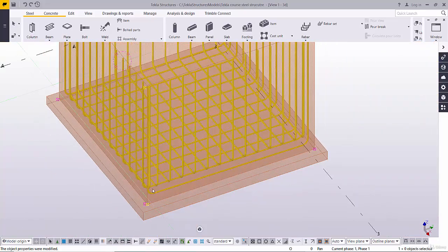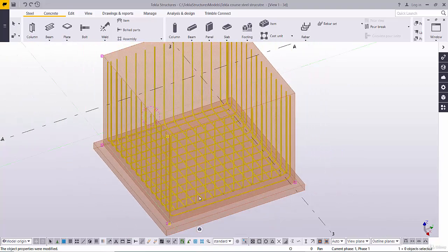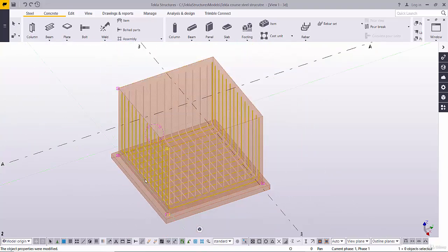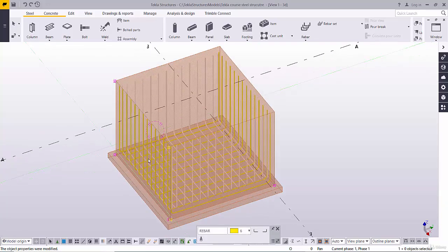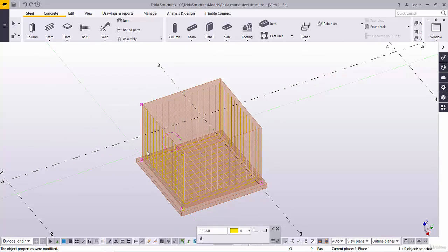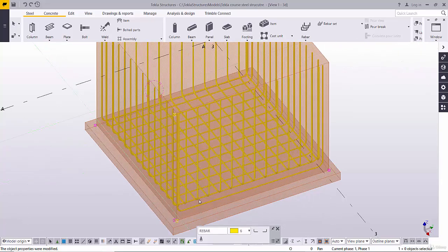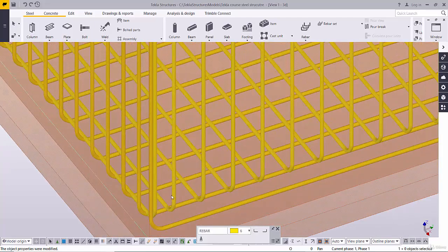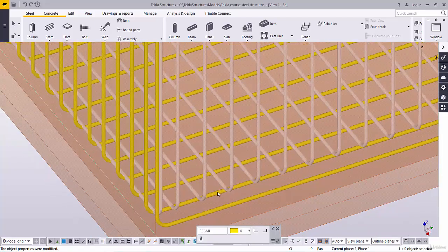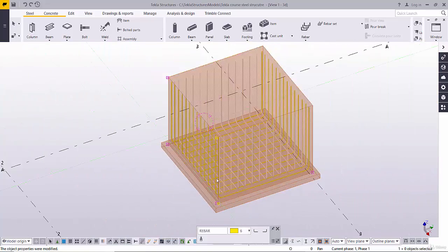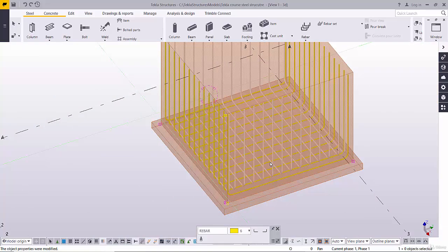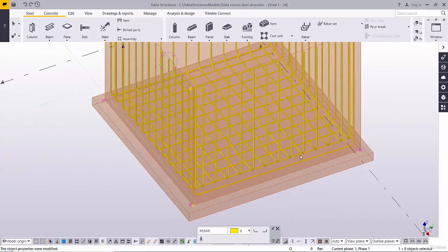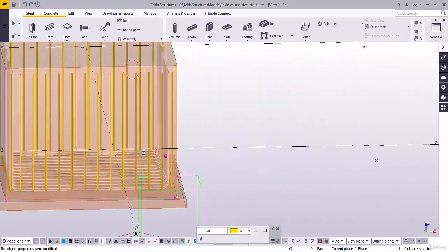The code tells us that the reinforcement of the foundation in the short direction is on the bottom, and here the rebar reinforcement in the long direction is on the top. Here we have a square foundation, so this is not important to do, but we must put one group of rebars above the other. Okay, so we can apply these steps in any direction.